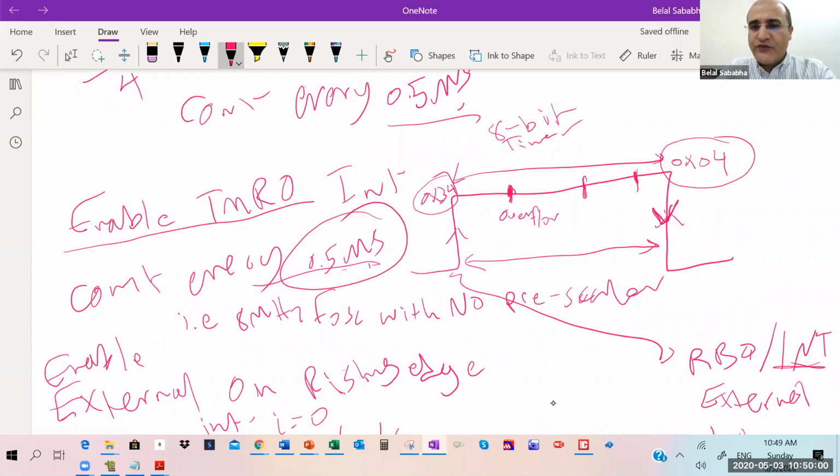So to count from 0 to FF and overflow takes 2 to the 8, which is 256 counts, from one overflow to the next overflow, and from the second overflow to the third, 256 counts, right? And from the last overflow to the falling edge, it is 4, right?